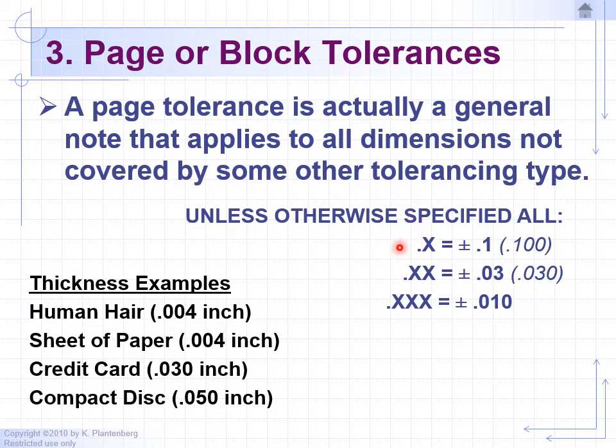So once again, if you give a length of, let's say, 1 inch, and it's only 1 decimal place, in other words, it's 1.0 inches, you're telling the machine shop to go into the title block. Again, you're not providing a tolerance directly on the dimensions, so they have to look in the title block, and they'll say, okay, 1.0, 1 decimal place, then we can be off by plus or minus 0.1 inches.